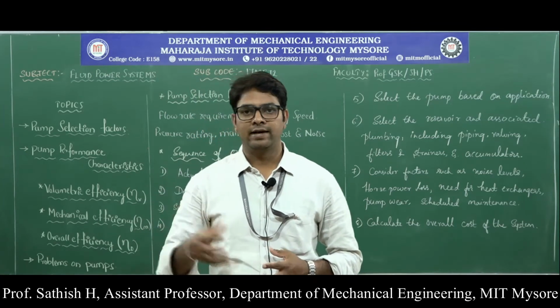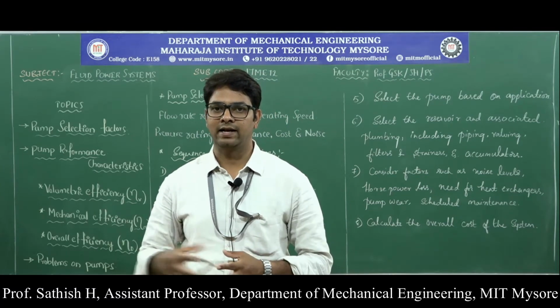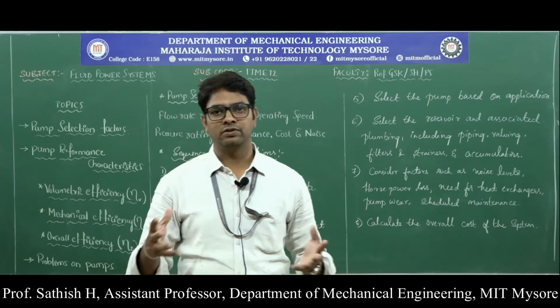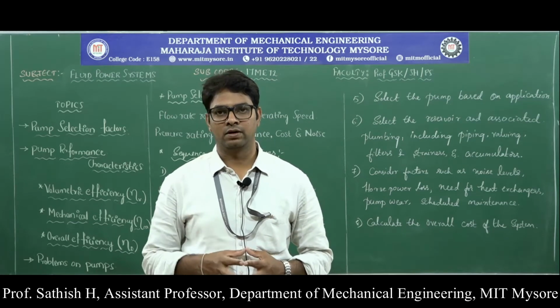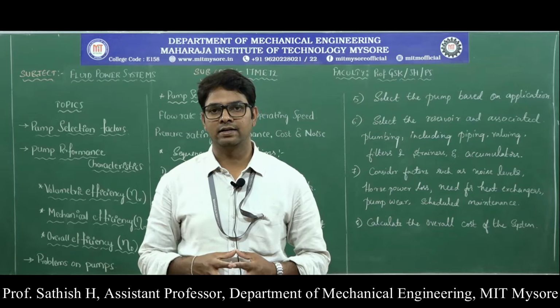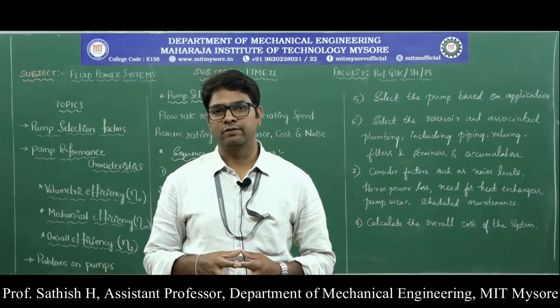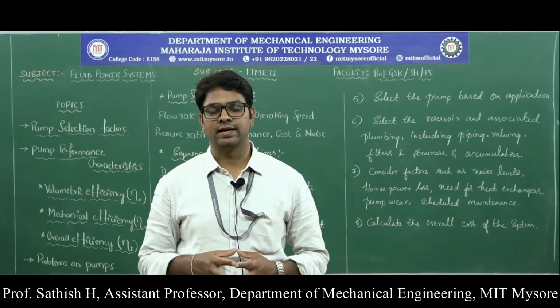We also have an actuator where the fluid energy is converted into mechanical energy, where the actual work is done. Then we have piping systems in order to connect all these components together, and of course the tank in order to store the hydraulic fluid. We also have other components like filters in order to remove the solid contaminants which are present in the hydraulic system.